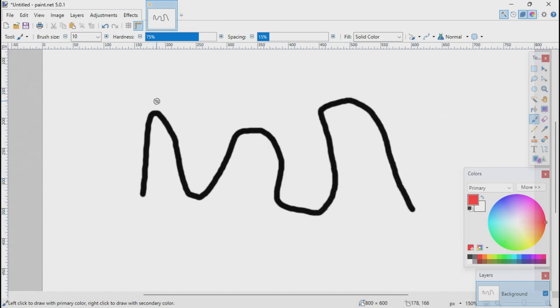The more points along the line that we sample it, the more accurate or sharper we can make that filter. So we got what we call taps along in frequency here. And this is a very poor way to explain it, but if I've got this many taps or points along it, then I can kind of approximate that.